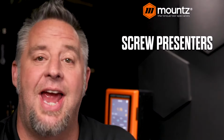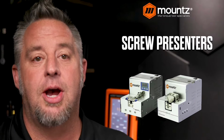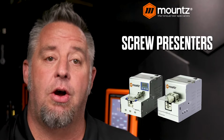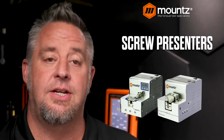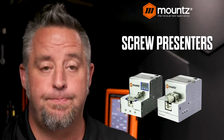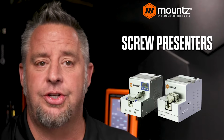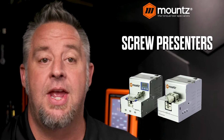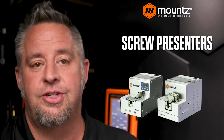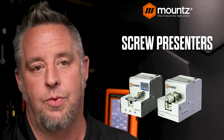And so as we look at the screw presenter, there are a couple different options that are available. There are screw presenters that are used for automation purposes, and those basically allow the fastener to sit in a turntable, and as that fastener gets pulled, the turntable will rotate and a new fastener will go in where one was pulled.